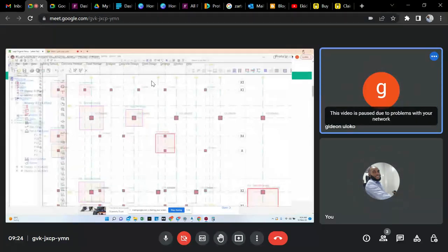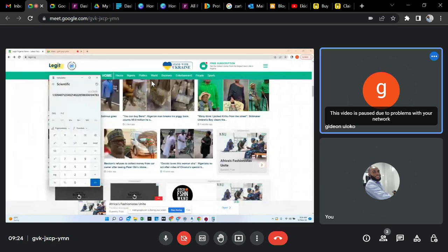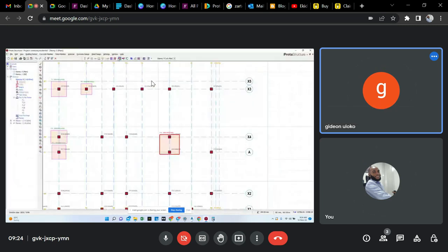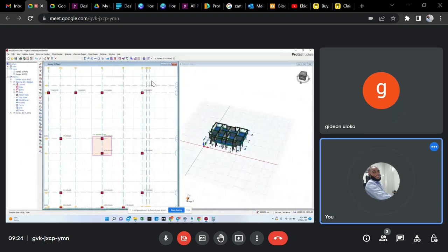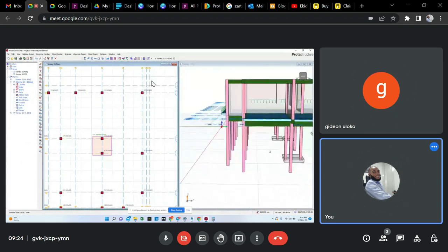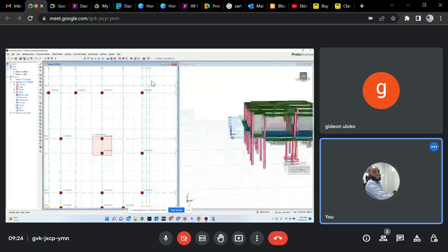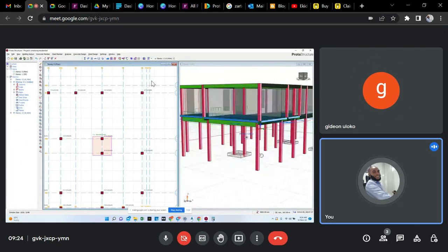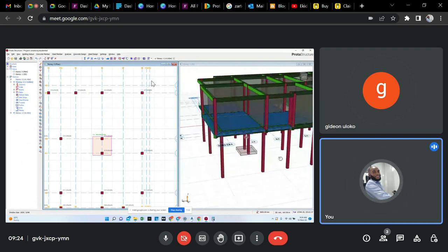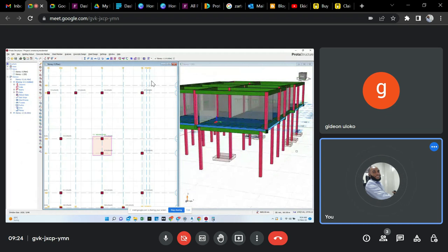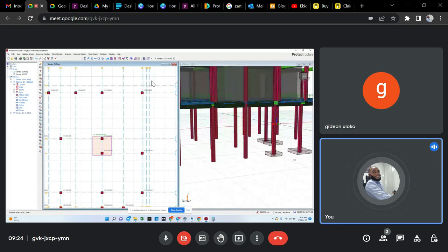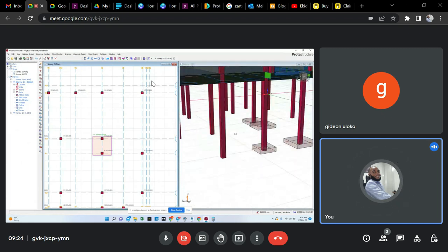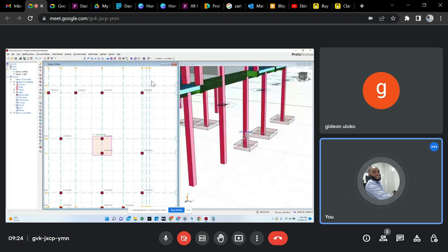3D view. Okay, so you can now see, zoom in on those footings. You can see that, right? So this is how to design for a single footing for a pad foundation and for a combined footing, and also how to reduce the depth, the footing width, if maybe the footing width is getting large, how to reduce it.